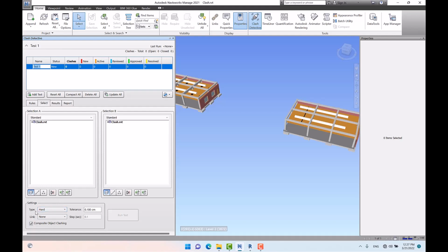Here as you can see, there are types of clashes, hard. Here if I open the drop down list, we got 4 types of clashes. For example, duplicates searches for mistakes in the models, elements that have been modeled twice, copies and so on. And clearance checks the required minimum distance between 2 items. In other words, it checks the items in which there is not enough offset between them. Clearance is called soft clash. Suppose that you have 2 objects in your project and there should be a specific distance between these 2. So it's the clearance's job to check the required minimum distance between these 2 items.